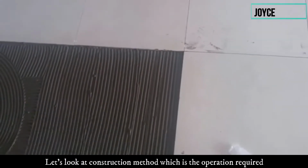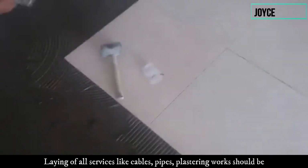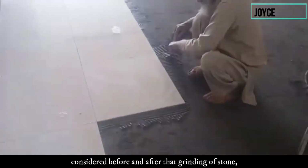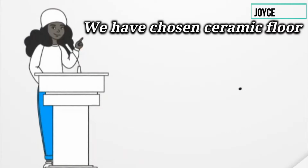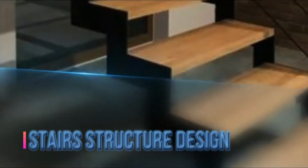Let's look at the construction methods, which are the operations needed before and after taking up flooring work. Laying all services such as cables, pipes, plastering, and fixing of doors should be completed before, and after that, grinding of stone, honing of stone, and also polishing of stones is needed. Here we have chosen ceramic floors, and one of the advantages is that ceramic floors are highly durable and can last over 20 years.